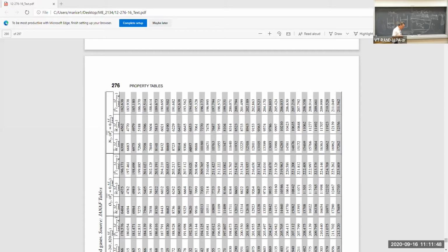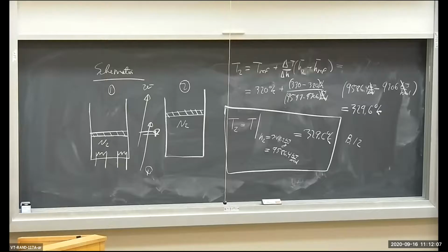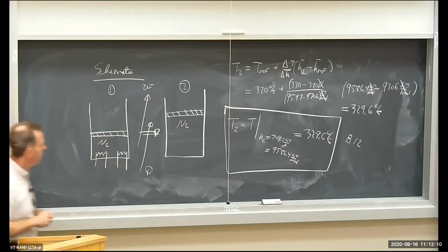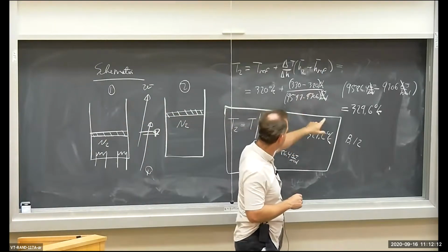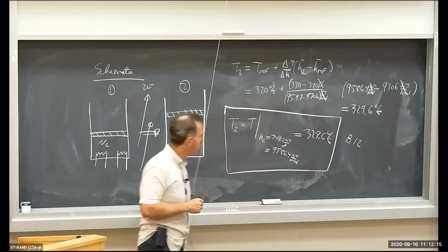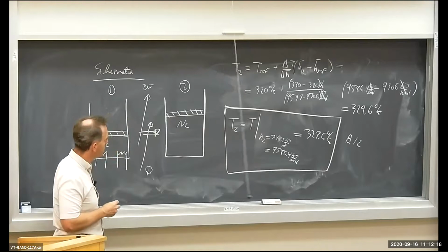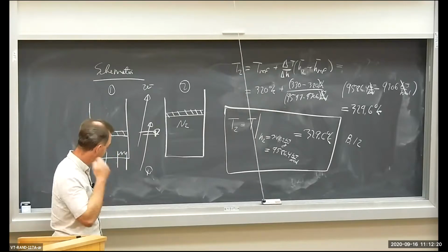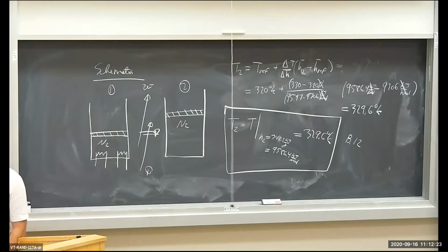This should be very close to the true temperature of the system in the final state of the process. Constant specific heat was an approximation, although we got very close to the correct answer, as I recall from last time. So, 329.6 degrees Kelvin after the linear interpolation of temperature using table B12, very close to the constant specific heat problem.